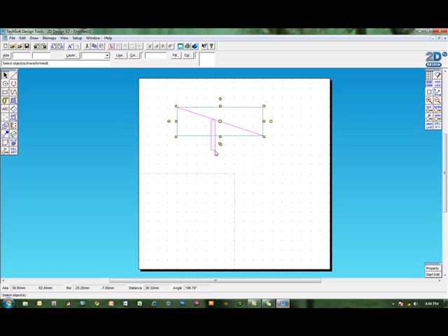So I'm clicking here, and as you can see, I'm trying to, firstly, even to select the object can be quite difficult. You actually need to select the entire object by left clicking, so you hold down the left click and you can select an entire object. If you select part of it, it still won't select it, or alternatively you can also click on the line if it's a line, or click on part of the object and it will help you. But again, if I try and left click now and move, it won't move my object. You must be hovered over the center to move your object.